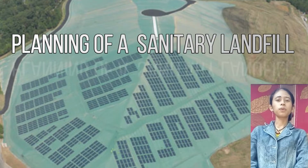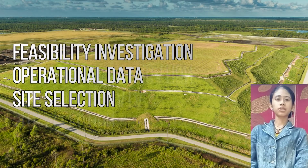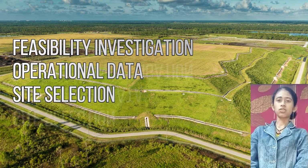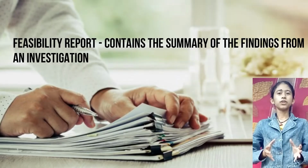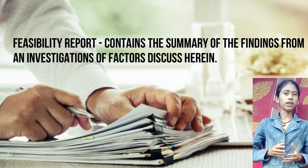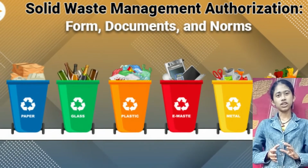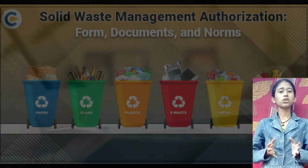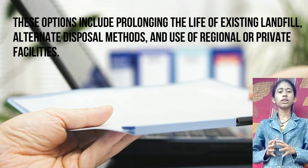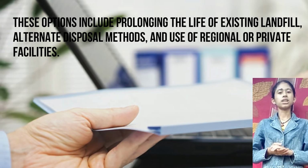Let's proceed to how to plan a sanitary landfill. Planning a sanitary landfill involves 3 steps, namely feasibility investigation, operational data, and site selection. The feasibility report contains a summary of the findings from the investigation of factors discussed herein and should include advantages, cost of waste recycling, volume reduction, and waste minimization. The options for a new landfill must start with an investigation. These options include prolonging the life of an existing landfill, alternate disposal methods, and use of regional facilities.